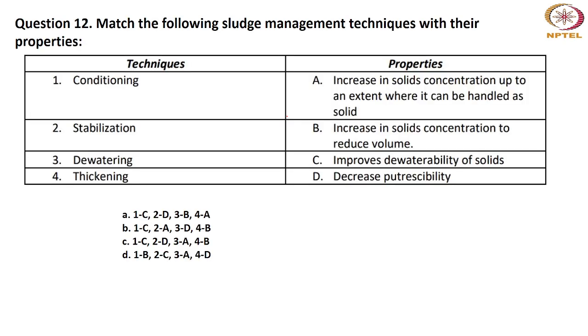Okay, so the correct answer is again option C here. You can see the conditioning phase improves the dewaterability of the solids, because maybe chemical conditioning, like with ferric chloride, is done before we go for the dewatering. So it will improve the dewaterability of the solids.